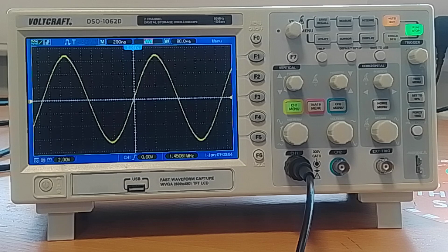The other two values that you get are values that you calculate. So the RMS, where you take the peak, the 6.8, and you multiply it by 0.707. And it's always 0.707 for RMS. And that gets you 4.8076. So you'd maybe write 4.81 for that. Volts, RMS.